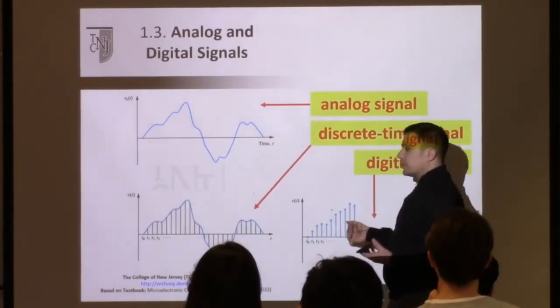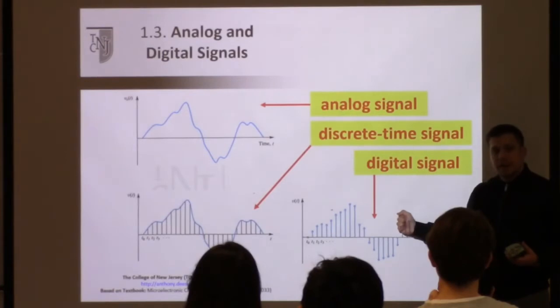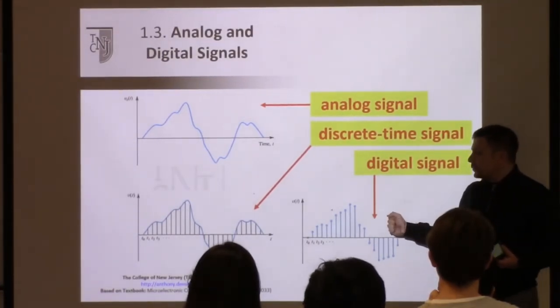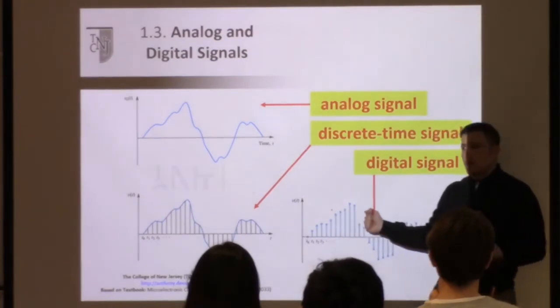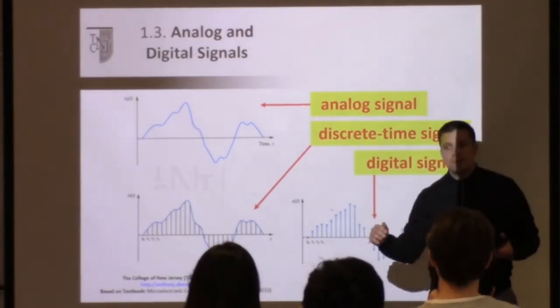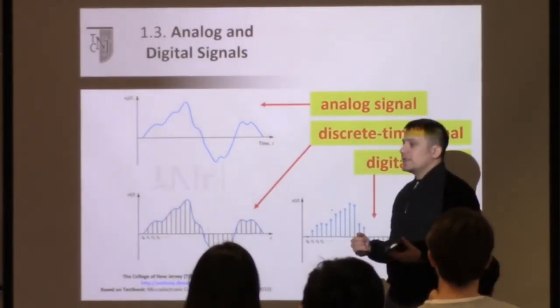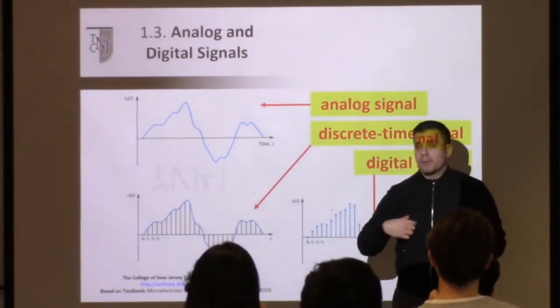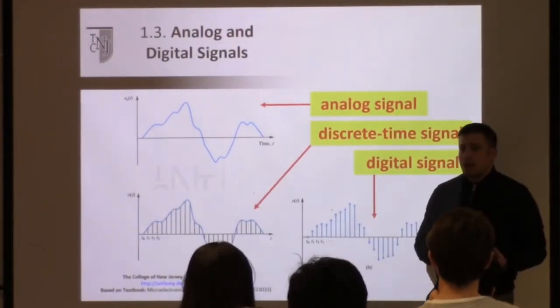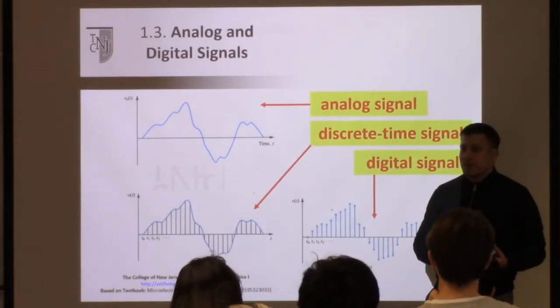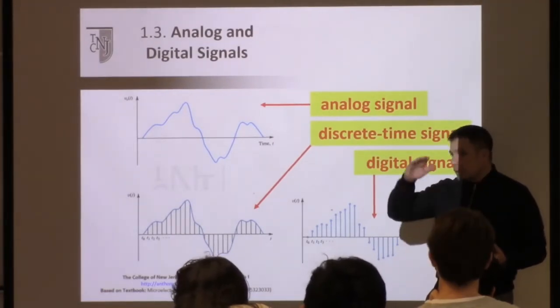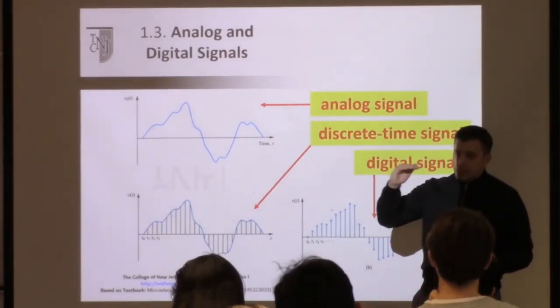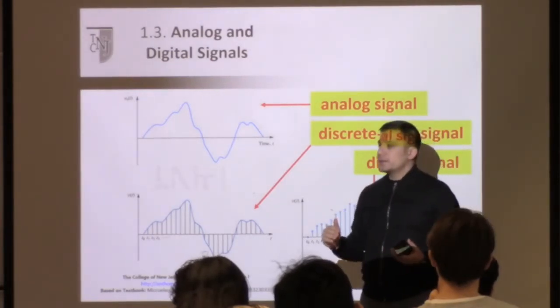That's going to be relatively difficult to represent in computer memory or some similar type of construct. So what we're going to do is quantize it. Quantizing is when we essentially round. What we say is that our values, we're going to set a resolution. We're going to say the voltage will have a resolution of 100 millivolts. And so we'll knock it up or down to whatever the closest 100 millivolt value is.